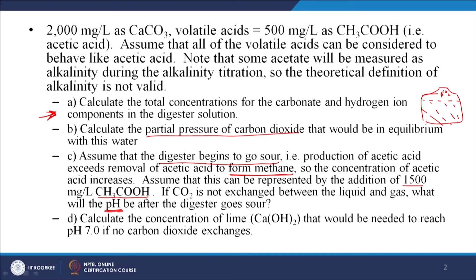Again, why do you need to calculate the pH now, right? In this particular anaerobic digester, you have different phases: hydrolysis, acidogenesis, acetogenesis and methanogenesis. And the relevant microorganisms that are required for acetogenesis and methanogenesis are active only in a very narrow pH range, I think 6.5 to 8 or 7.5. Do not take my word for it, but anyway near the neutral pH.